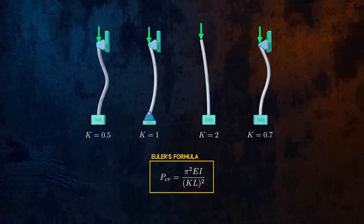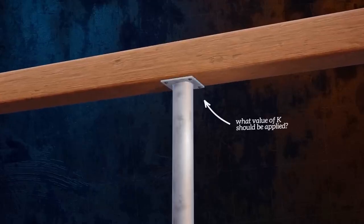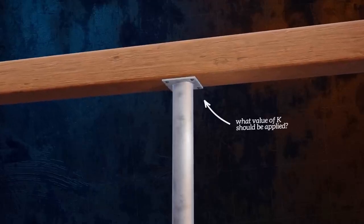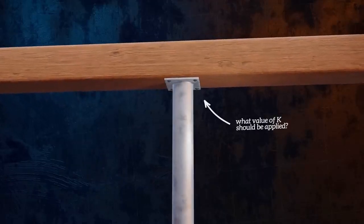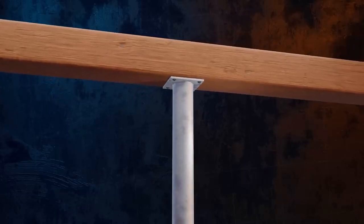End conditions clearly make a huge difference to the critical buckling load and must be considered very carefully. In real-life applications, it isn't always clear which effective lengths should be used, and the amount of restraint at the ends will depend on the stiffness of the adjacent members. Design codes often provide guidance on conservative assumptions that can be used for these scenarios.